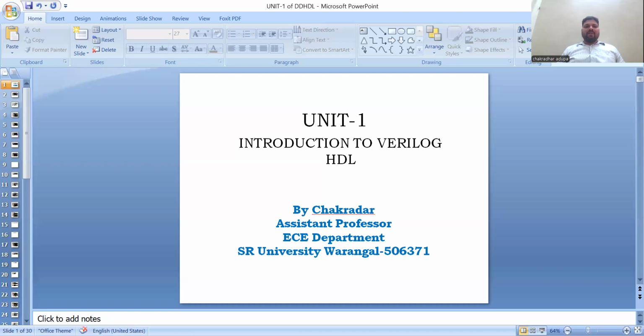Next is gate level. Within the logic level, the characteristics of systems are described by logical links and their timing properties. All signals are discrete signals, and they can only have logic values 0, 1, don't care X, or high impedance state Z. The four possible values are 0, X, 1, or Z. The usable operations are predefined logic primitives, called AND or NOT.